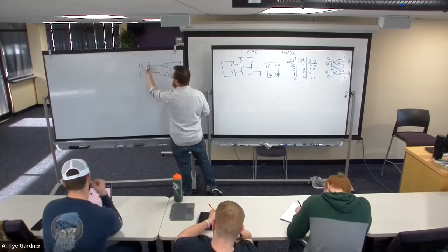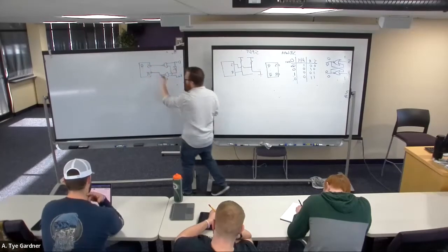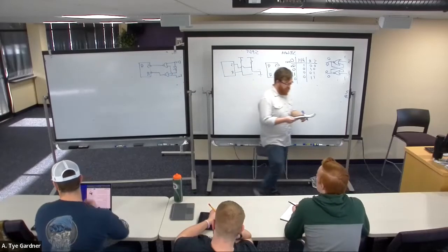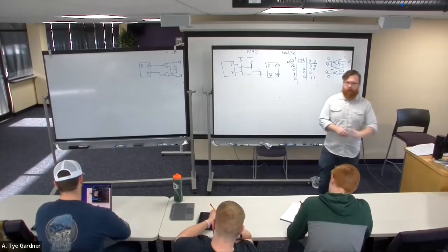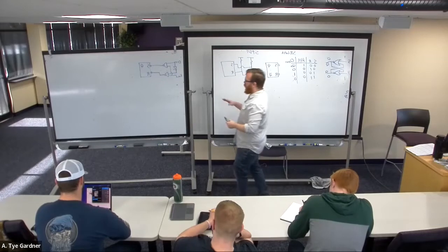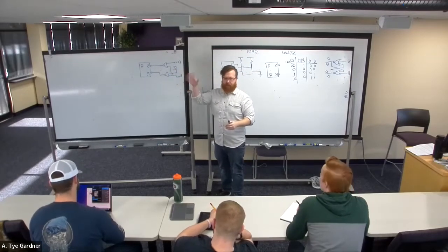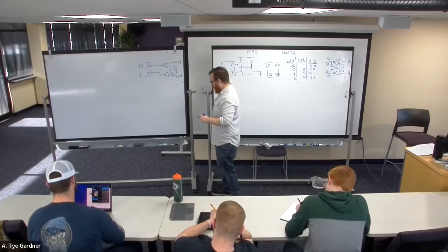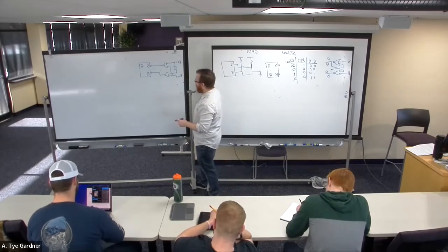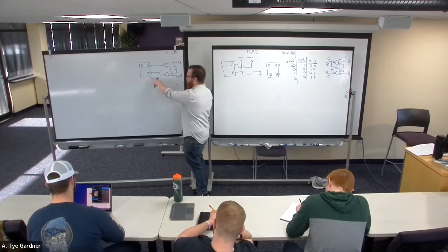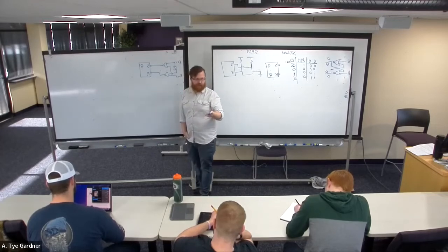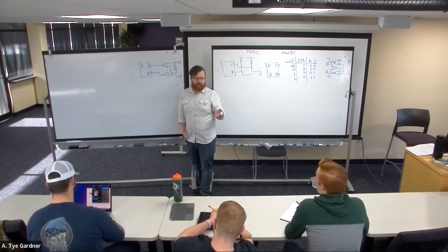And let's start with active lows here because they're NAND gates, because this is going to make it easy. All right, so now this is a D latch, all this combined. But let's talk about what's happening with it. The first thing that I'm going to do is simplify. We want to use universal gates because they're size optimal, right? They're easy and cheap to design.